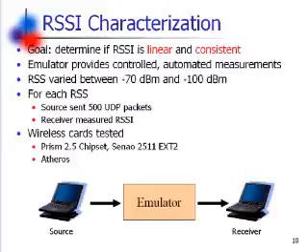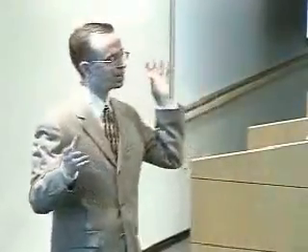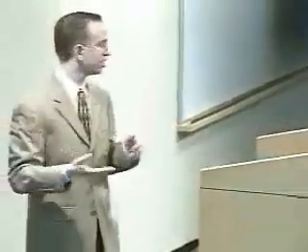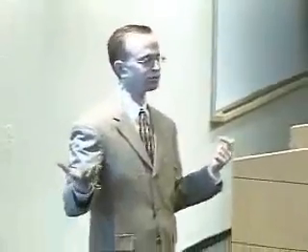And in particular, whether it's linear and consistent. So to do this, we use the emulator to hook up a transmitter and some receivers. And we sent packets and had the receivers measure the RSSI. And then we saw how accurate they are. So we sent packets between -70, which is very strong, and -100, which is very weak.